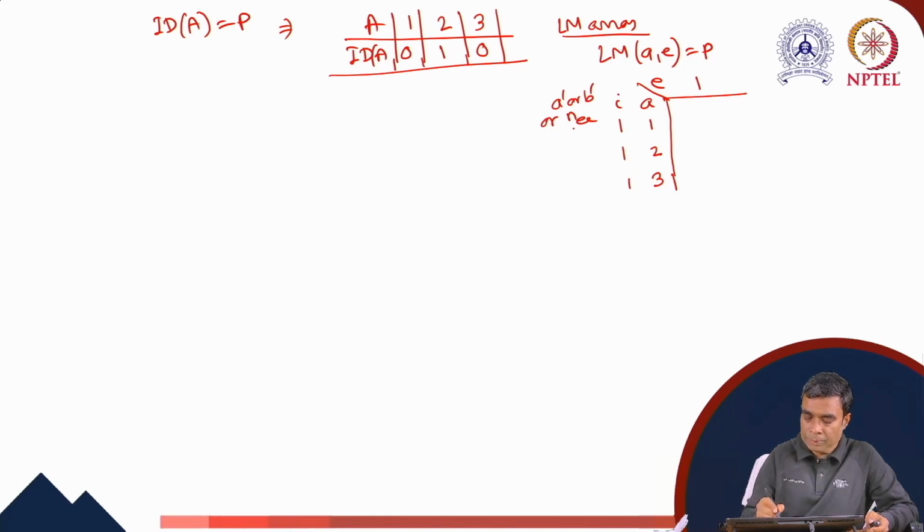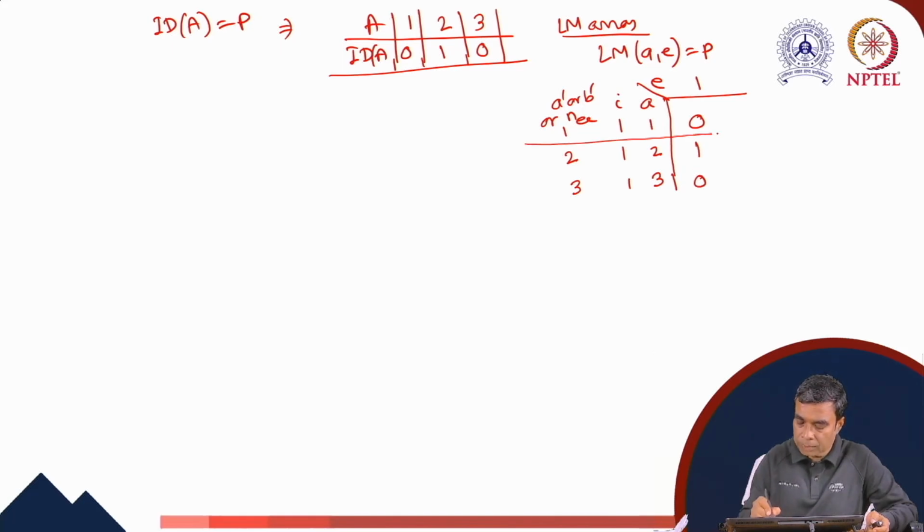So for element level equations, we can have a maximum of 3 equations, those equations can be 1, 2, 3. Now for the first element, first local node, the global equation number is 0. For the first element, second node, the global equation number is 1. And for the first element, third node, our global equation number is 0.